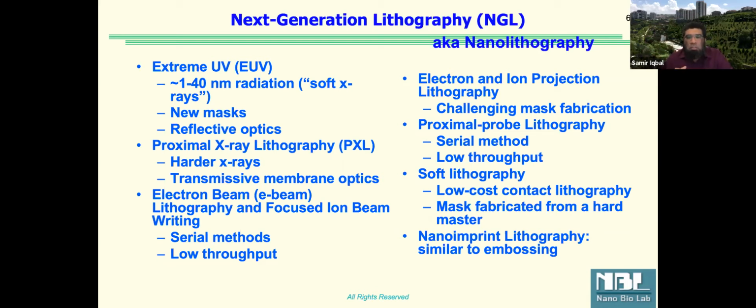It's just going to transmit through. An optical material is supposed to change the direction of the rays, right? That's how we can focus things. But X-rays just pass through. So that's another problem. You need to have a special kind of optics. You need to create a different kind of mask because it can go through virtually everything.